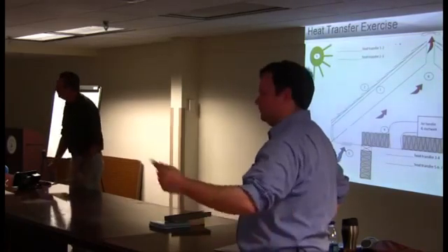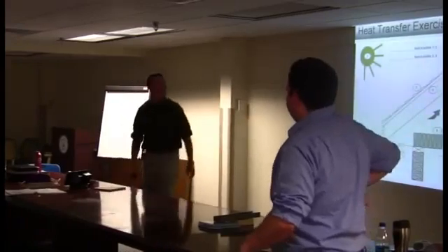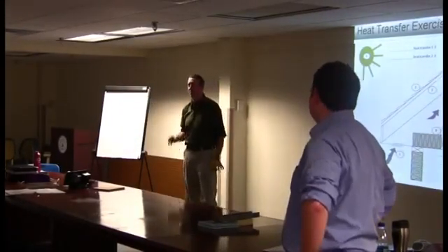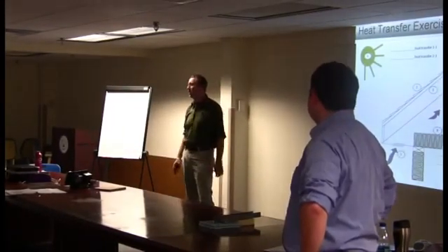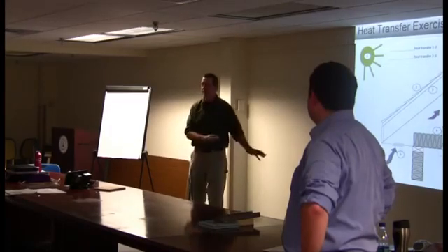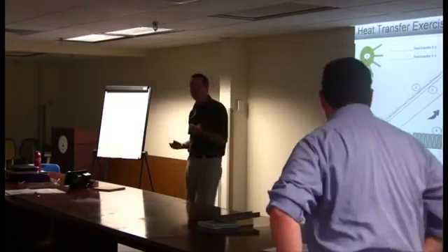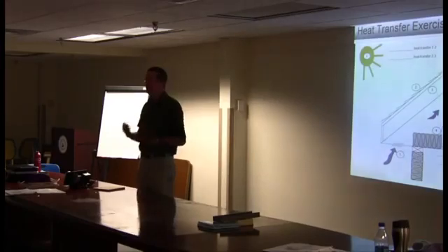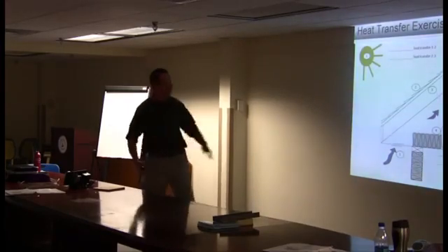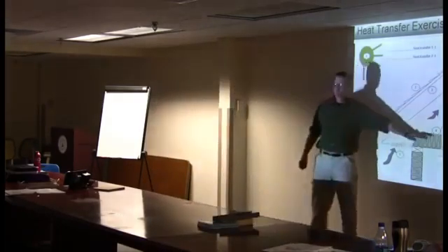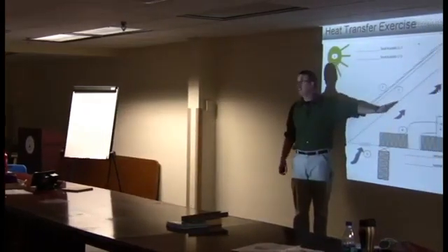Yeah, we could go along, we could change our envelope. And I want to emphasize that I think for commercial buildings, this is what we should do a lot. I think venting roofs is kind of a little bit of what we think is a good idea because someone told us it was. Residentially, a lot of times we have a flat ceiling. Basically, if you have this assembly, yeah, you probably should vent above it.